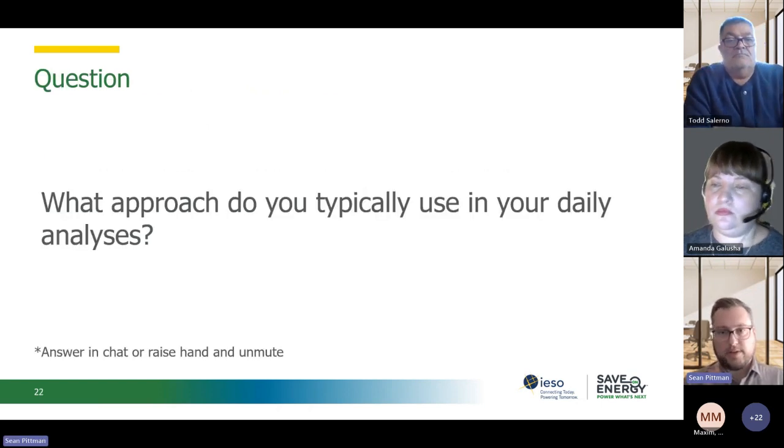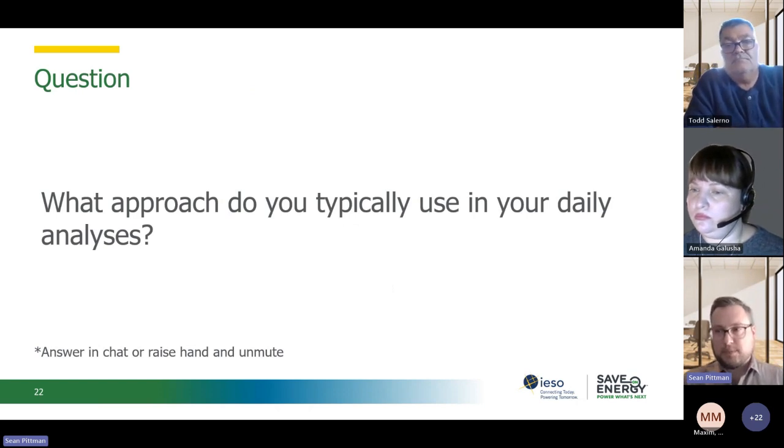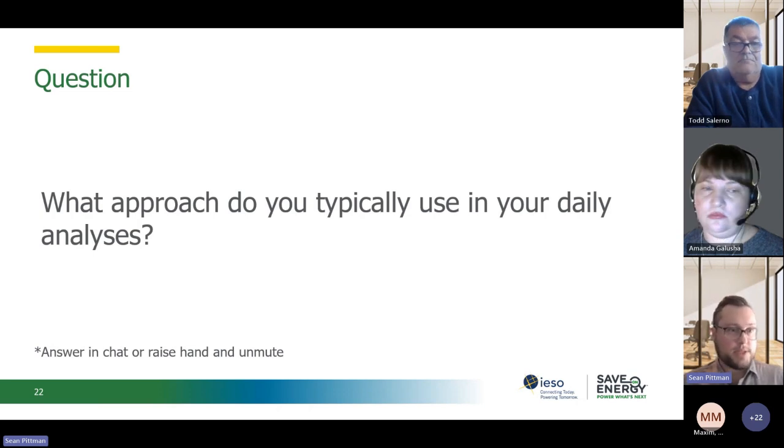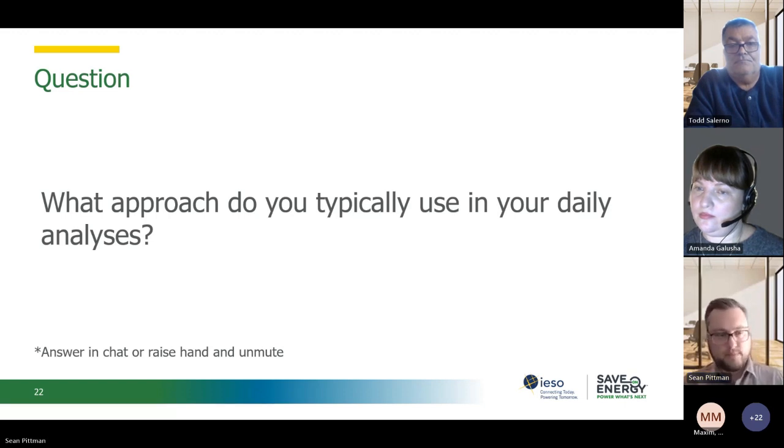So, a question again for the group: what approach do you typically use in your daily analyses? If someone asked you how much energy is being used by your process cooling system, what approach would you use? Would you use a very basic approach and say, I know on average it draws this many kilowatts, we run 12 hours a day, 12 hours times our kilowatts times the year, that's how much energy it uses? Or do you have an Excel model already built that takes in more information than that? Both approaches are acceptable, depending on what your needs are.